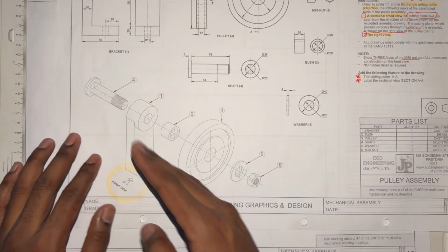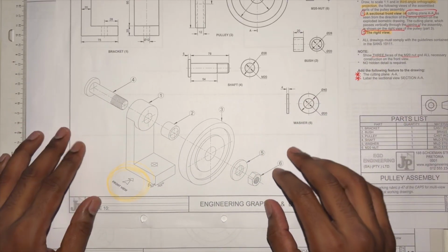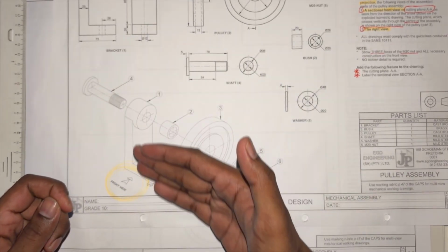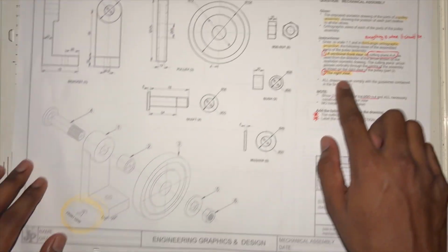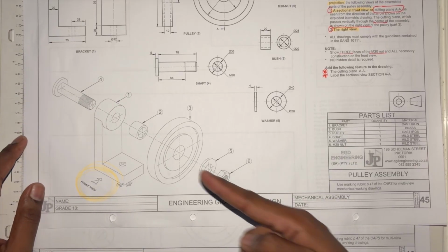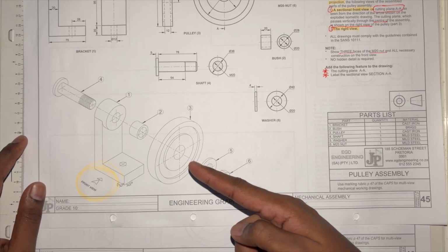So clearly we need to cut through this front view somehow, observing the cutting plane. Okay, so the front view is what we're going to draw, but obviously sectioned according to the cutting plane that's given. Then they want a right view. So if that's the front, that'll be the left. That's the right view. So we are looking this way at the casting and we're going to draw that.